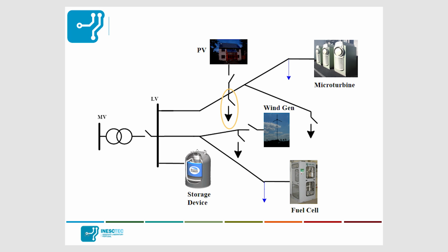Afterwards, we can start energizing the grid. And then it is possible to connect more loads, and at the very end, to connect more PV generation, more wind generation, non-controllable generation. In this way, we arrive at a situation where the island is back in operation and is capable of operating in an islanded manner.